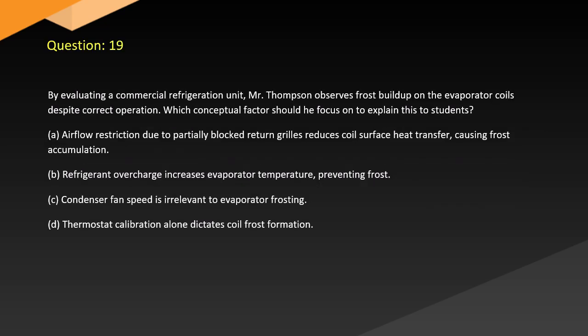Question 19. By evaluating a commercial refrigeration unit, Ista Thompson observes frost buildup on the evaporator coils despite correct operation. Which conceptual factor should he focus on to explain this to students? A. Airflow restriction due to partially blocked return grills reduces coil surface heat transfer, causing frost accumulation.